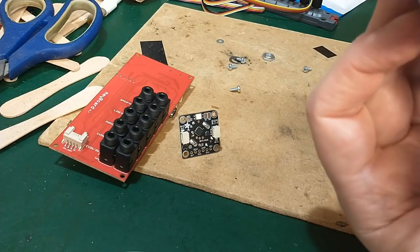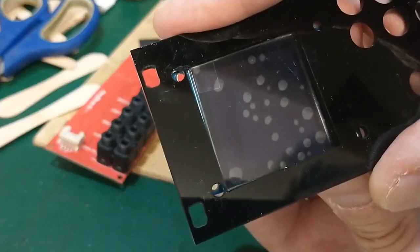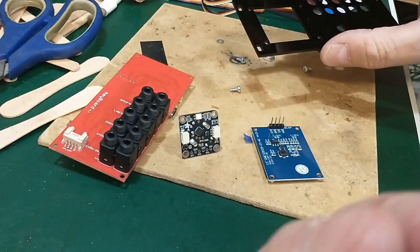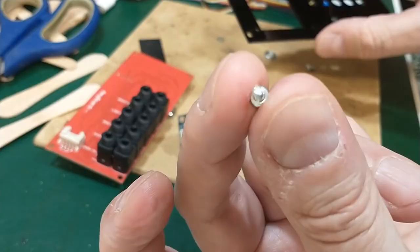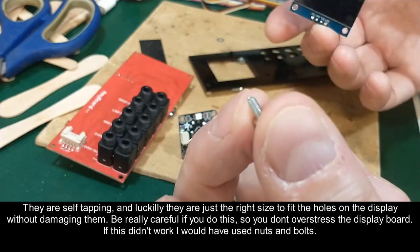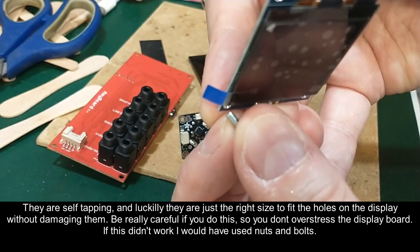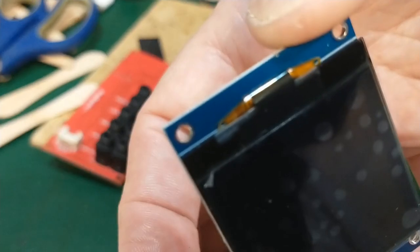sort of are slightly misaligned, and it's a bit rough, but I've got some self-threading screws here. They're not self-tapping, they sort of cut their own threads a bit, but I found that these will just go into the holes and there's enough play in them to get them to grip onto the holes on the screen.